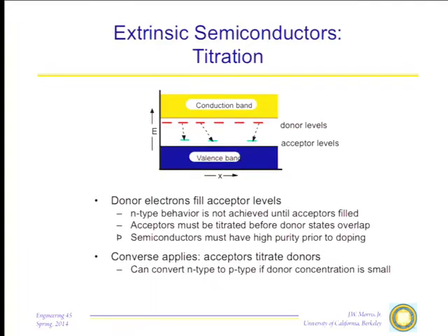But you see, any donor level that has an energy higher than the donor level I'm putting in will not affect it because the donor levels are filled. Any donor levels slightly below this won't affect it either because those donor levels are filled. The only things that can affect this are any empty levels, no matter what their energy may be, that have lower energies than the donor I'm putting in.